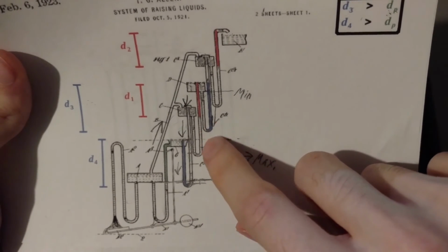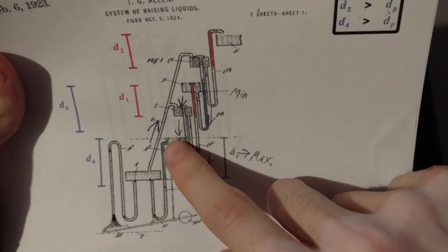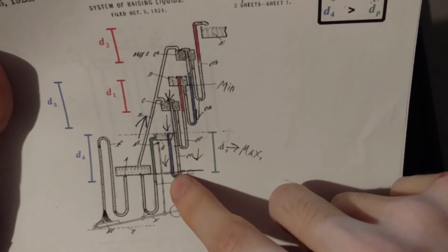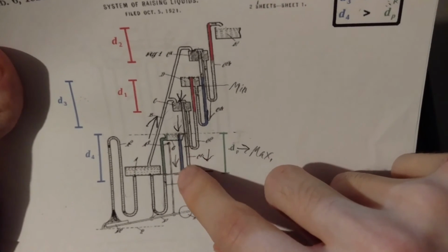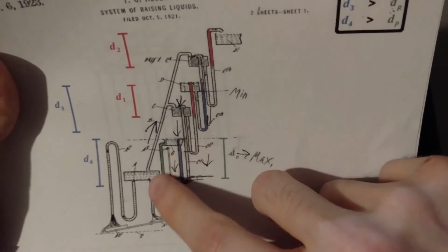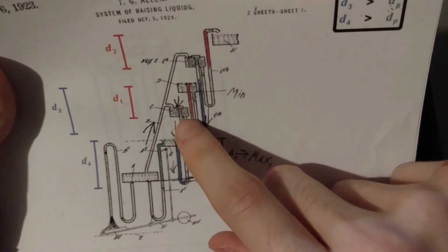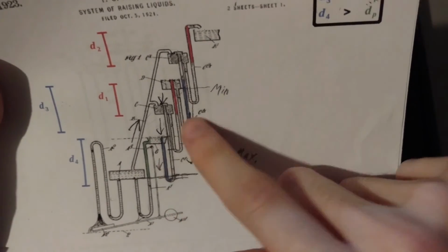In this case I did put the blue on the other side because the pressure is being generated from the water line in the feed tank going down to the bottom of the trap. So, that's your back pressure. That's what pushes the water up through this tube and up to this point. So when there's air being pushed out through here, you want to make sure the air can't get pushed past this trap here.